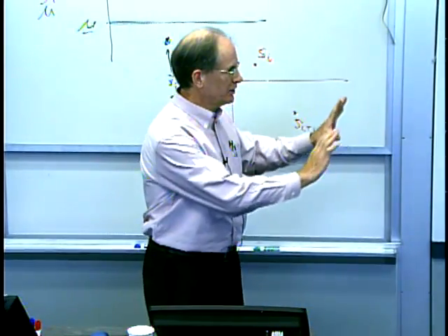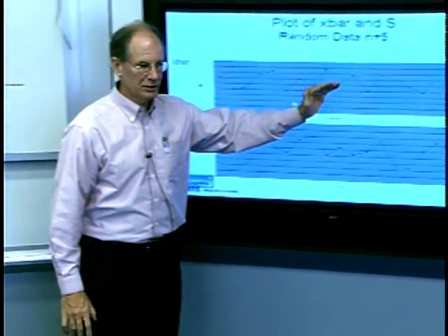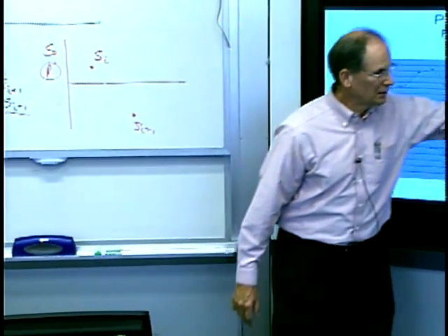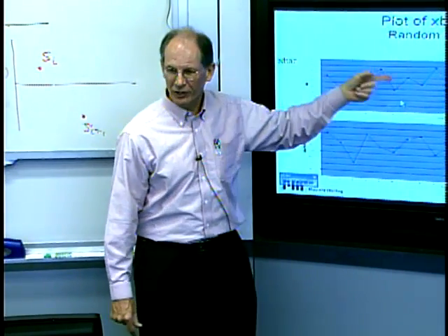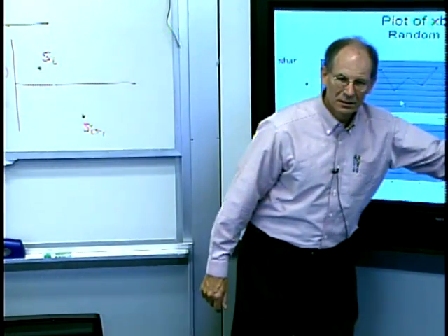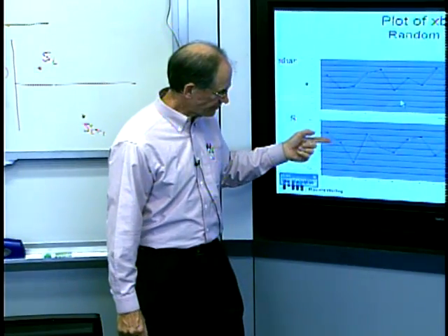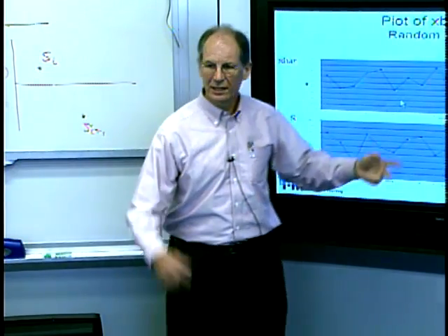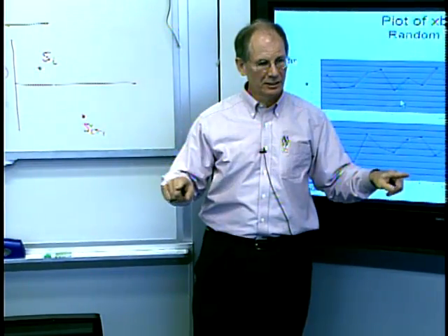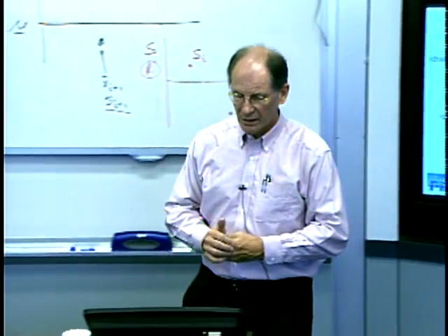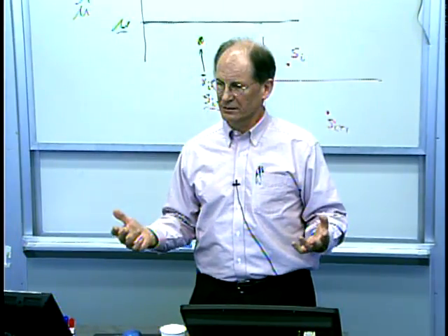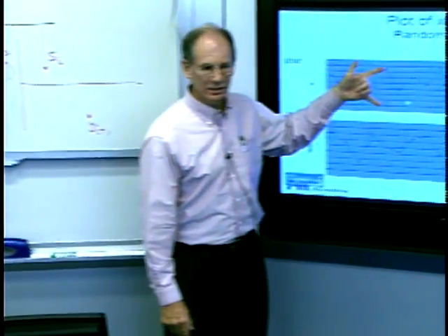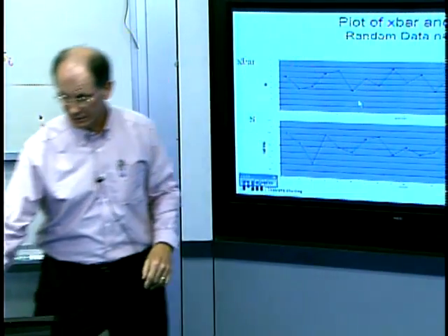So this is what you get. You plot a new data point, and this is what you start to expect. Now, of course, I can look at this and get a grand mean, which is an average of all the average values, and a grand standard deviation estimate. And say, okay, now I know the underlying distribution of the process. Once I say that, then I know what to expect, right? Now I can put some lines on this chart and say, this is where the data should fall if everything's in a state of control.